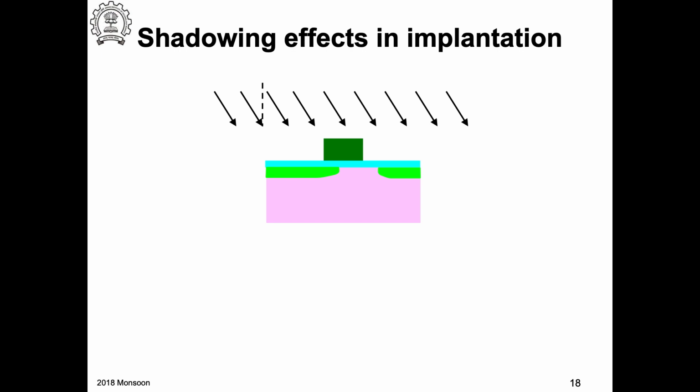And when you do this process, in this case, I have no control on this junction. I would lower the potential here, but not at the junction. So this device will not work. But here I can control the PN junction. I get the channel, and this is reverse bias.